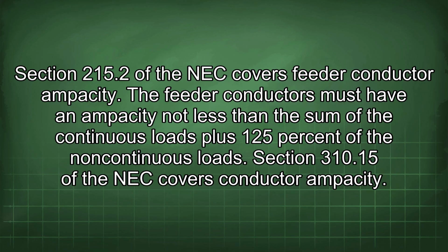Section 215.2 of the NEC covers feeder conductor ampacity. The feeder conductors must have an ampacity not less than the sum of the continuous loads plus 125% of the non-continuous loads. Section 310.15 of the NEC covers conductor ampacity.